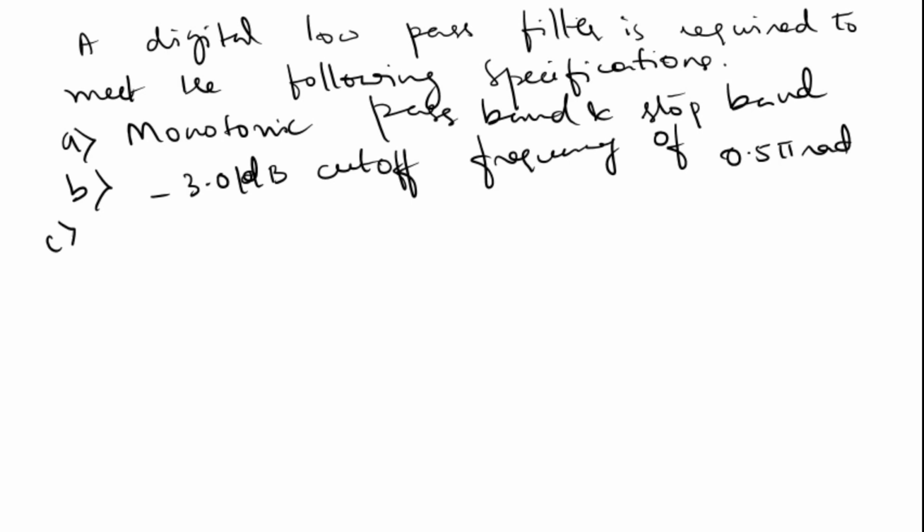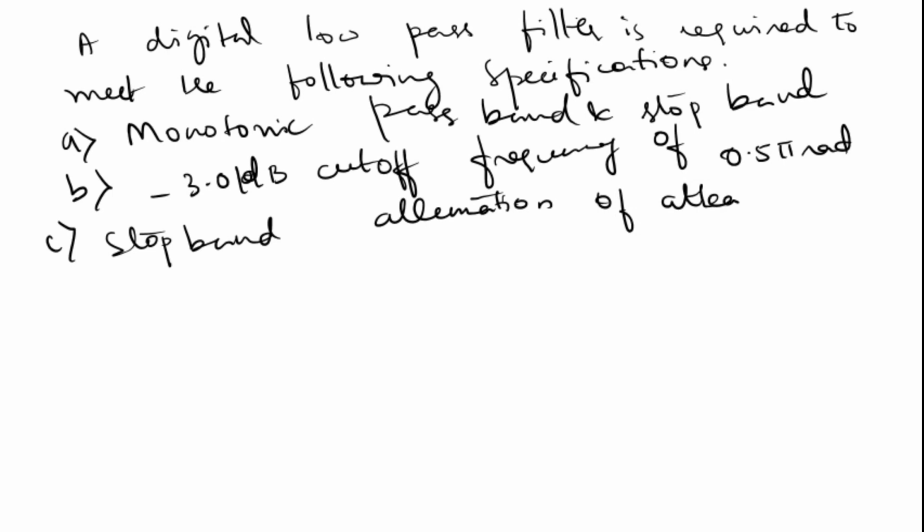And third one, stop band attenuation of at least 15 decibels at 0.75 pi radians.